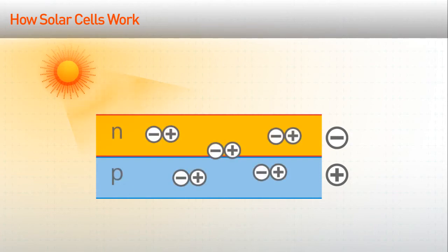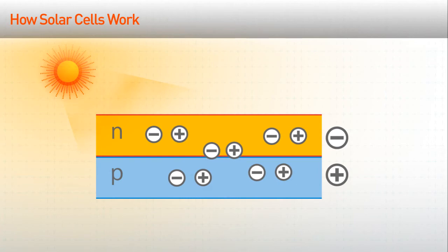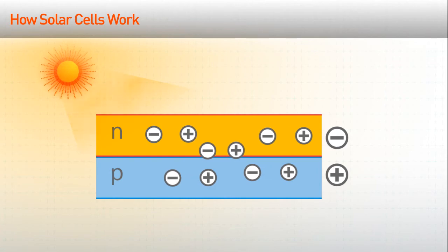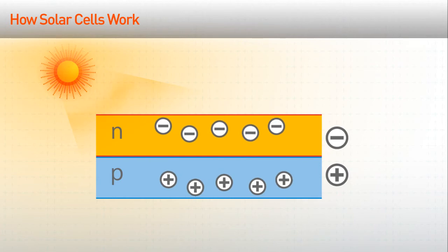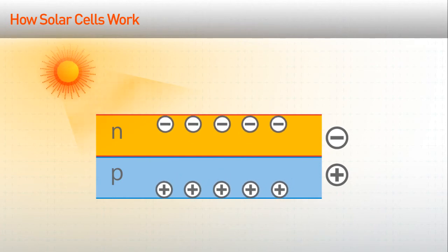When sunlight shines on the solar cells, the photon energy excites the electrons in the semiconductor material to produce electron-hole pairs. The electron-hole pairs are subject to the internal electric field formed by the p-n structures in the solar cells and then driven to separate. This causes electrons to move to the negative electrodes, while the holes move to the positive electrodes.